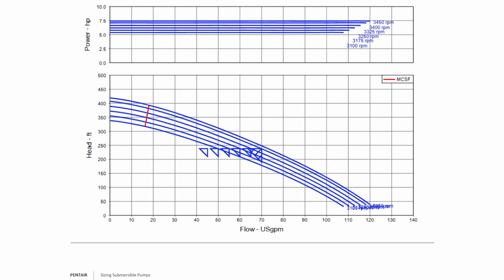If you can explain to the customer that with the investment of a variable frequency drive, you can flow as little as, say, 50 gallons per minute versus flowing to full 70 gallons per minute. And at 50 gallons per minute, you'll be running only about 5.5, maybe 5 3/4 horsepower. So you'll be saving amps in the motor, which saves heat in the motor, which extends the life of the motor, and it also consumes less watts.